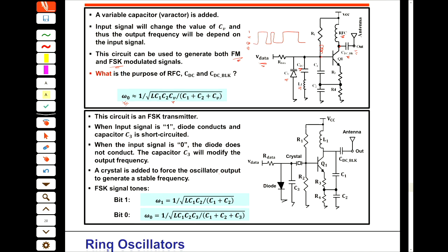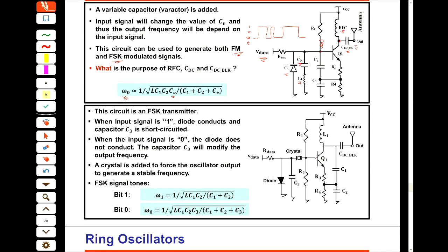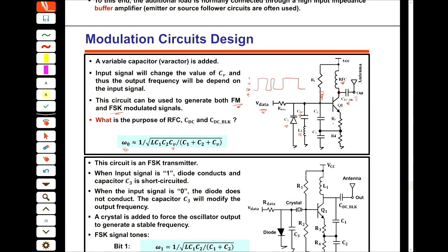All right. So in the second circuit, the bottom one, we have something kind of similar. Okay, here, what's the purpose of the R3 and R4? What was your answer? Yes, true. To tune the output offset, actually. So we can tune the offset.